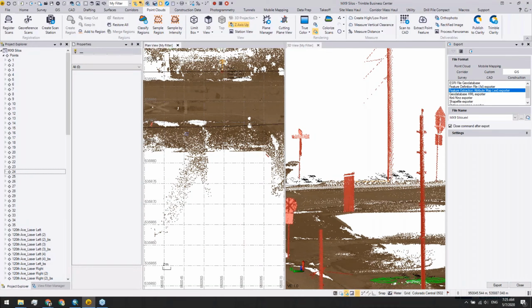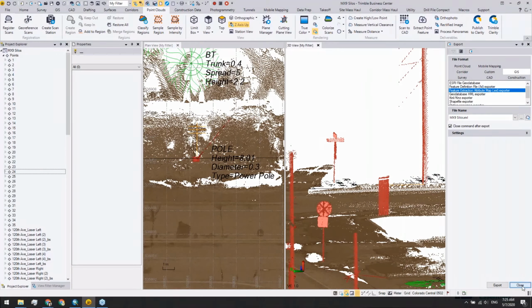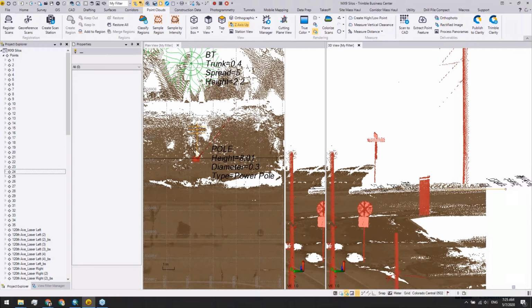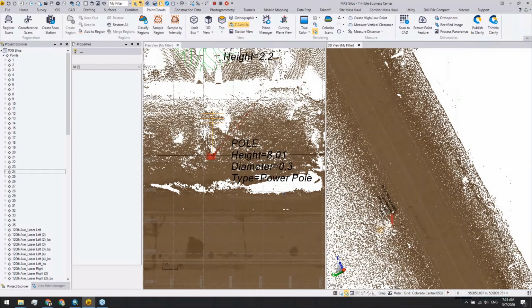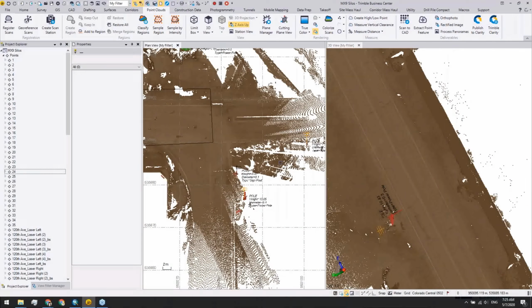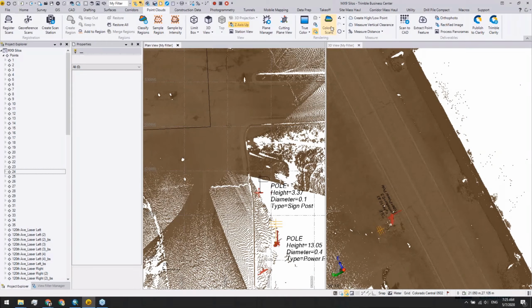All right, there are a lot of other types of point features that we want to extract, but they are not available using these manual or automatic modes yet. Then how do we extract them? For example, here I may want to extract a manhole from my road surface. How do I do it? To see the manhole better, I'm going to change the rendering method.